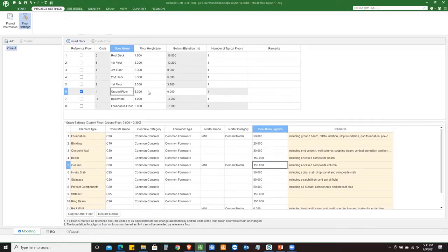So now the answer to the question of height is basically coming from here. The software identified those columns and input the same floor height that we provided, which is 3.3. Now, each one of these columns has a height of 3.3. Let's have a look at that.